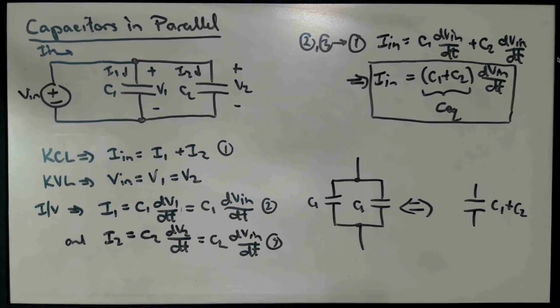Okay, so capacitors connected in series combine with a parallel operator, actually like conductances in series combine with a parallel operator. Can't remember if we actually explicitly said that or not, but that turns out to be true. Conductances connected in parallel add just with a summation if you think about their conductance. So capacitance is sort of analogous to conductance in the way that these elements combine with each other in making equivalent circuits.